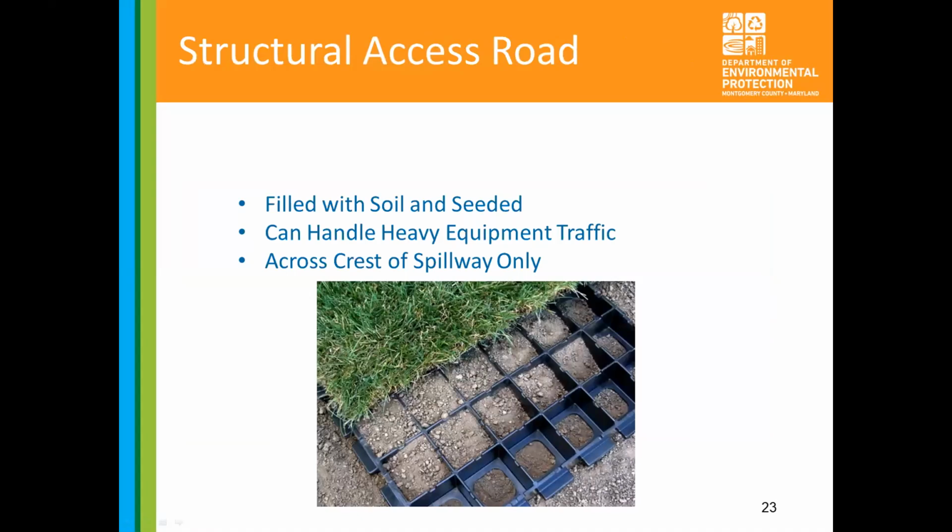As I said, there is going to be an access road along the crest of the embankment. It's similar to the gravel layer, where it's the subsoil and then these structural cells, which are rated for heavy equipment, so there's no real chance of it breaking under the loads that will be applied. It's also going to be filled in with topsoil and seeded grass, so you're not going to be able to see it. But it also provides passage in case any maintenance needs to be performed, and you can mow it under your standard maintenance procedures.